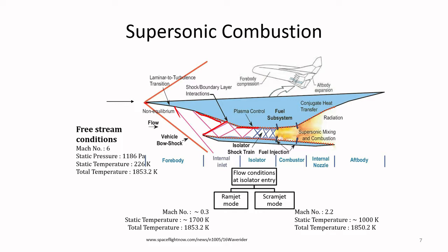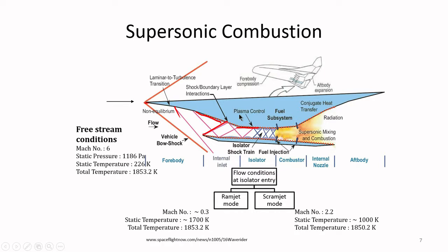But if somehow this pressure rise reduces the mass flow rate too much, then there is a possibility that even a normal shock can form in this inlet, and of course then the whole flow becomes subsonic and your scramjet combustor is lost. Okay. The whole thing breaks down, the flow becomes so subsonic that the temperature rises. So you really cannot afford that.